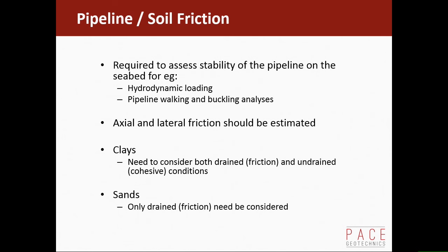In clay soils, I don't know if Mo did much on this. We usually consider clays to be an undrained material and to have a cohesive strength, an undrained shear strength we call it. And the notation for that can be SU or CU. We tend to use it pretty indiscriminately. I think SU is probably what you'll most commonly see. But if you go to America, you're more likely to see CU.